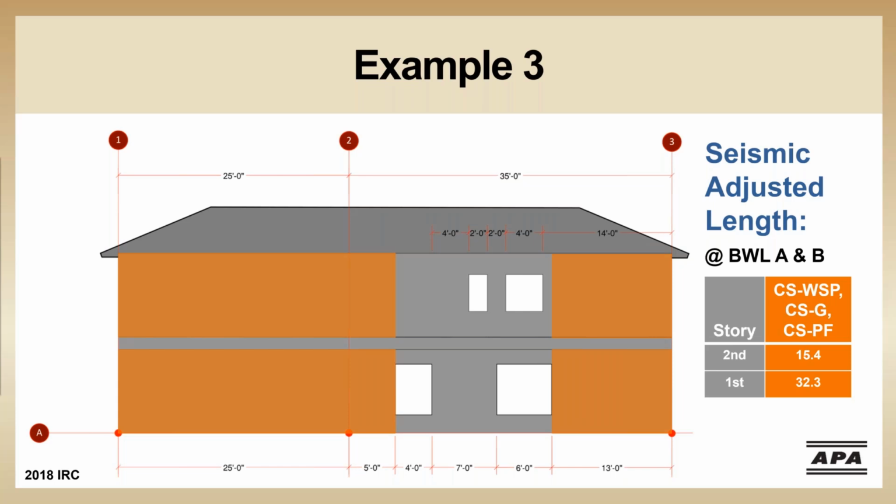A prescriptive approach works very easily for these walls. Note, we were able to avoid concerns about irregularities by placing our highlighted braced wall panels away from where the windows stack over each other. We'll consider braced wall lines A and B as good using prescriptive code.